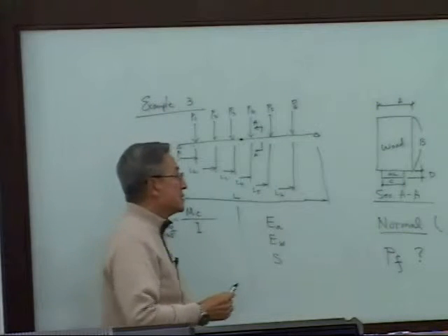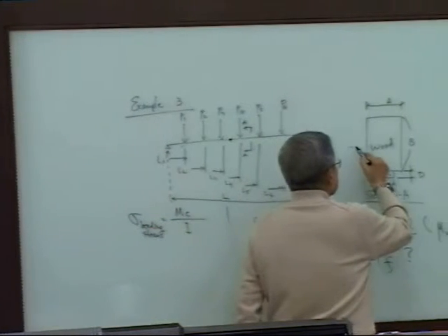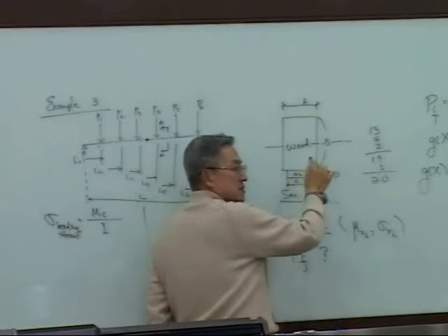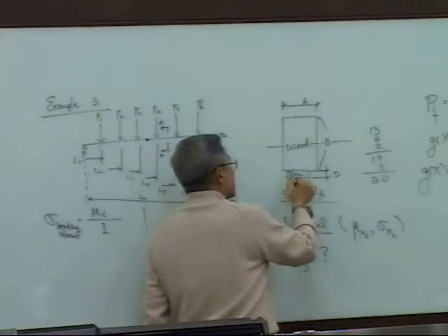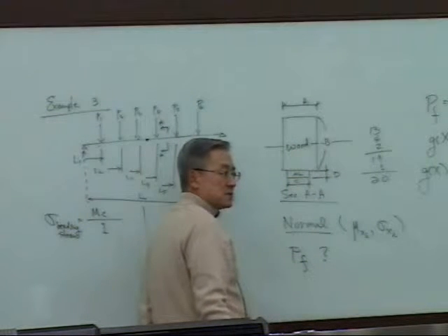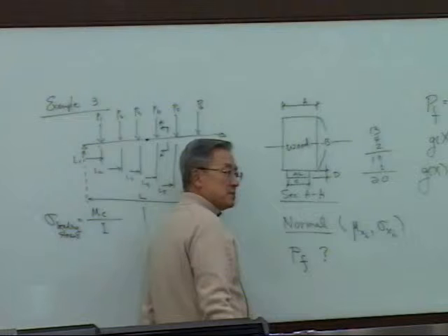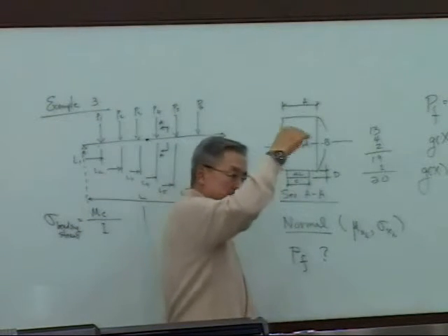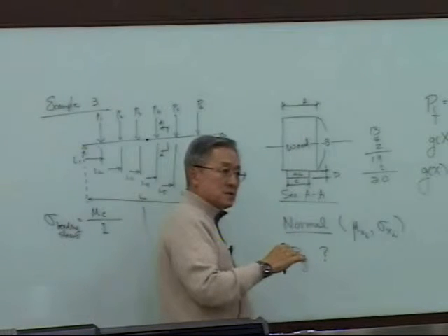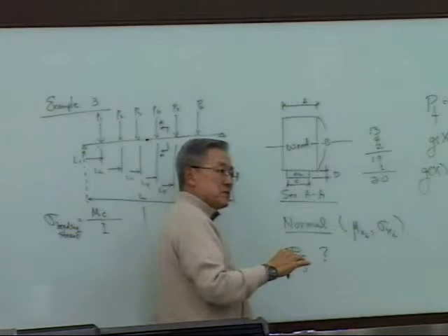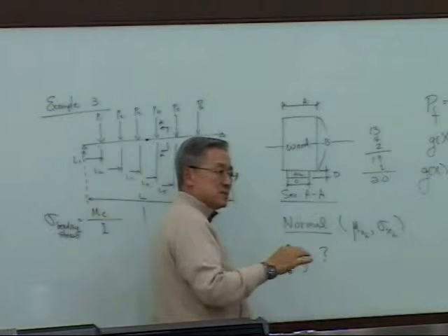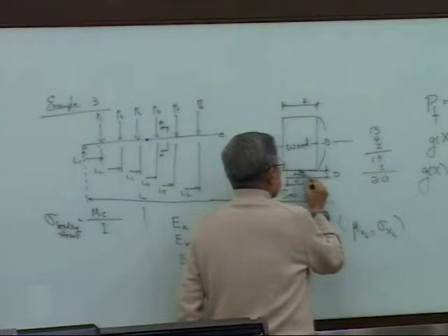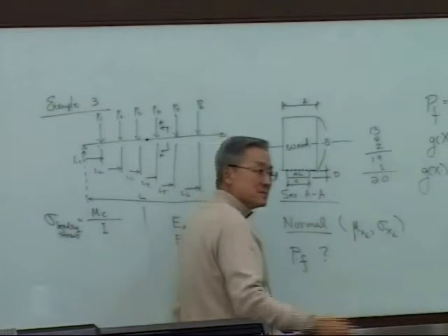What's the C? C is simply, this is all symmetric, cross-sectional. So where the maximum bending stress occurs, top or bottom, depends on the loading. In these loading situations, it's a downward static loading. So maximum bending stress is positive, which means it's a tensile loading right here, right? In this surface, right?